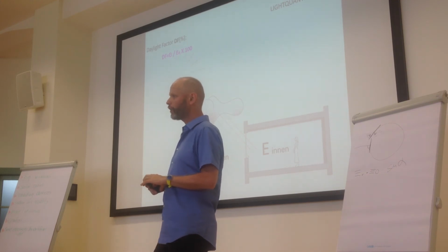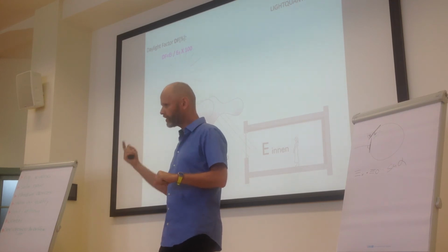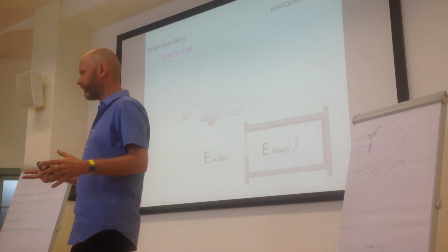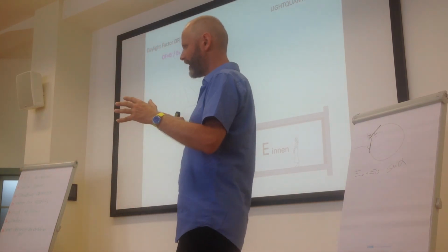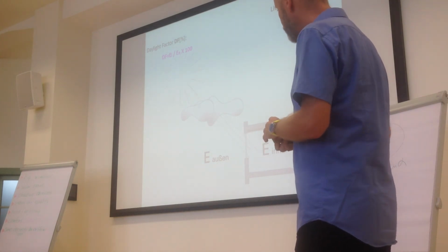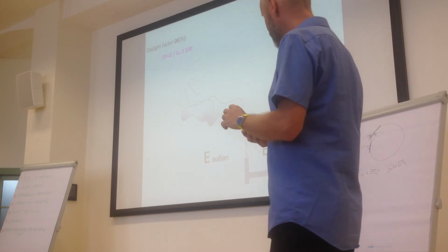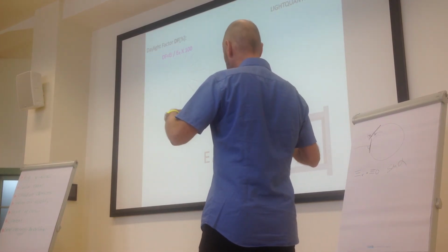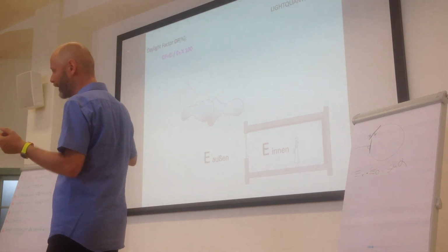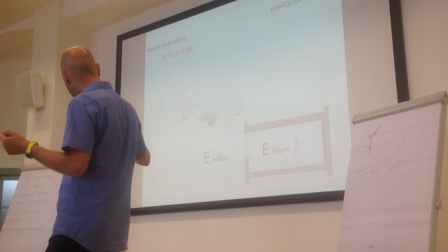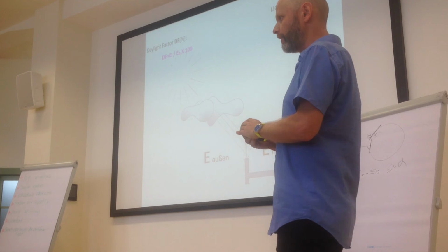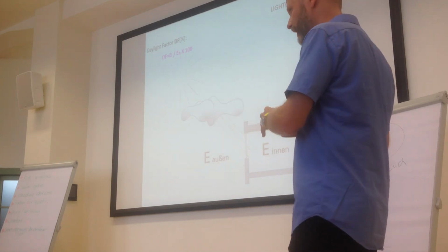We already heard that the direct light impact is constantly changing. It depends on the latitude, the season, and many other things. But a constantly overcast sky with its characteristics is always the same. And with these comparable circumstances, we can now calculate a certain unit, the so-called daylight factor. And the daylight factor is nothing else than a ratio between the illuminance level, the lux level, inside and outside.